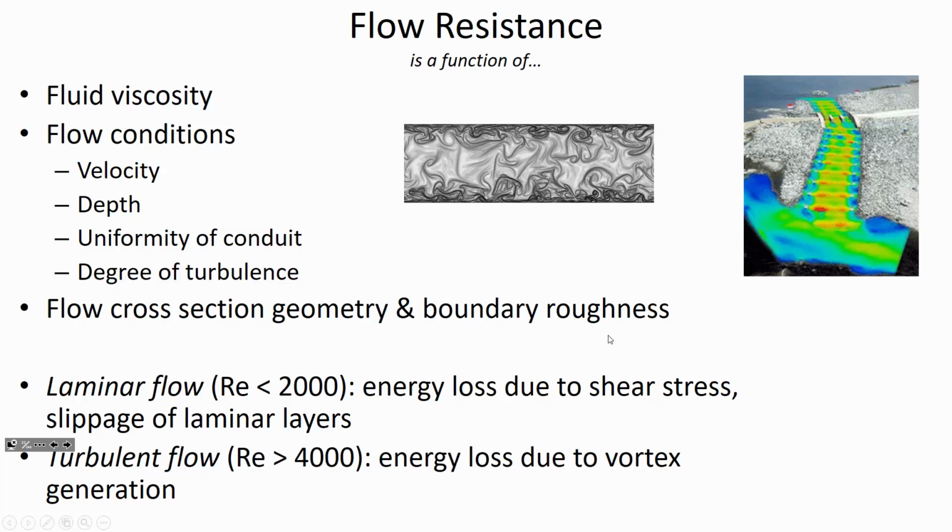And we'll talk a lot about the boundary layer, which is the thin cushion of water right at the boundary of the pipe wall, and how the roughness elements projecting into the water can affect how much energy is lost.